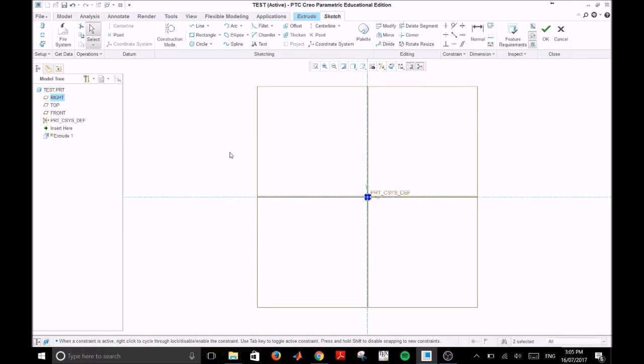We'll now have a more detailed look at some of our drawing options. A tab that you may have discovered, even if accidentally, is the construction mode. If we select it, any lines or features we draw will be dashed lines, and they won't actually appear in the extrusion. For example, we can make a reference line, middle click to finish, and it will be rendered as a dashed line. If we turn construction mode off, we can then align other features off that construction line.